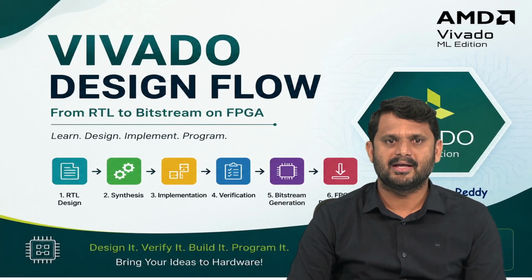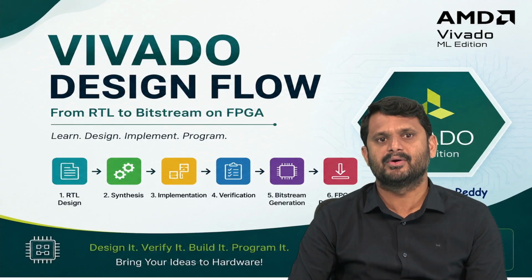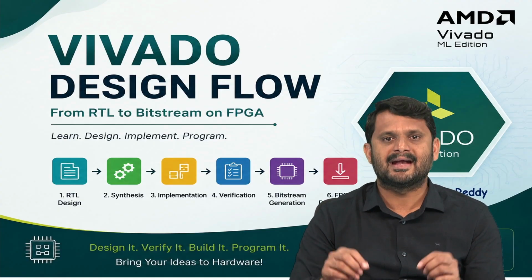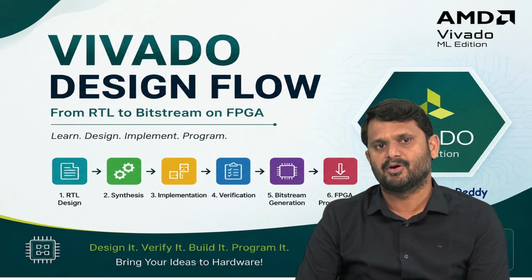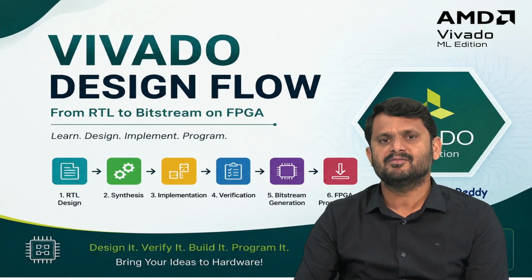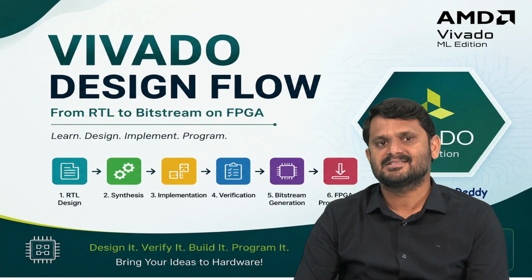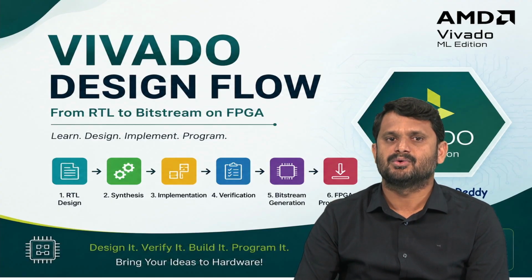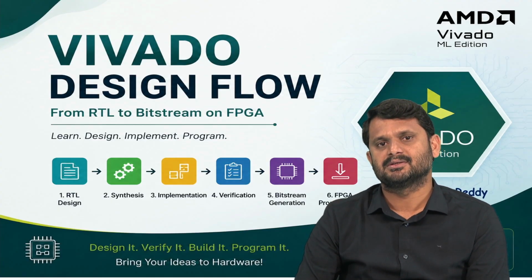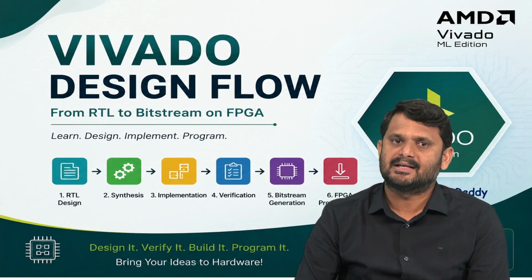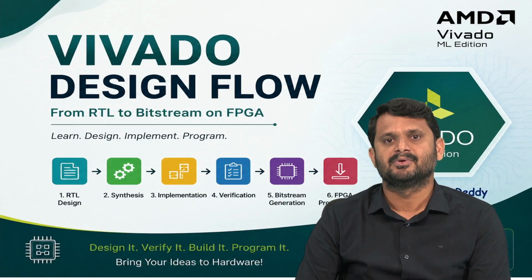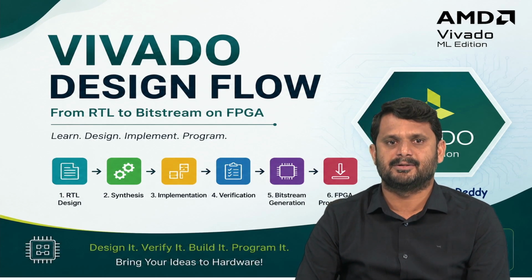In today's video, I'll explain the complete AMD Vivado design flow. So we'll start from the Vivado home screen and understand each step involved in developing an FPGA design using Vivado. By the end of this video, you will have a clear understanding of the entire workflow. From creating a new project, adding design sources and constraints, running a simulation, synthesis, implementation, and timing analysis. Finally, we generate the bitstream.